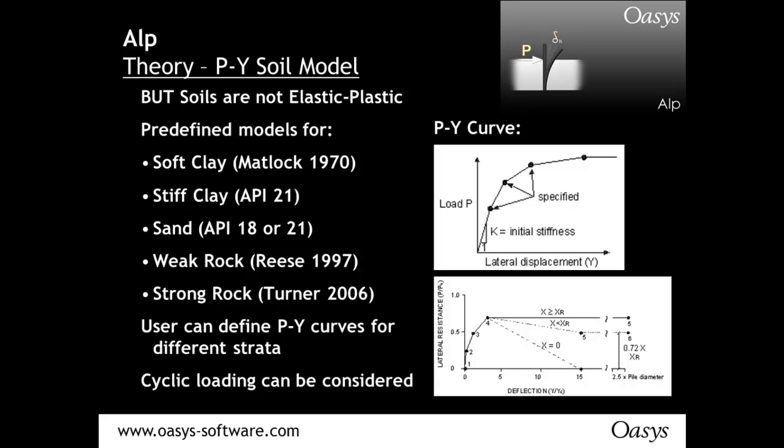You can also look at cyclic loading. So that's why ALP is very popular, for example, for looking at projects where you've got wind turbines, or maybe you're looking at wave loading on the pile. So these kinds of things are very popular with ALP.